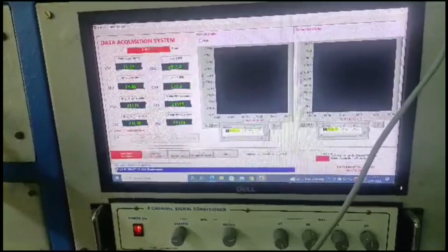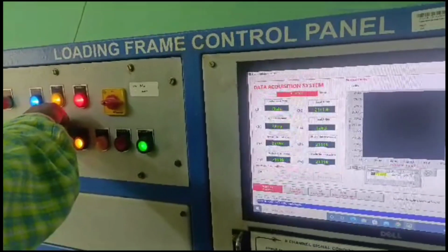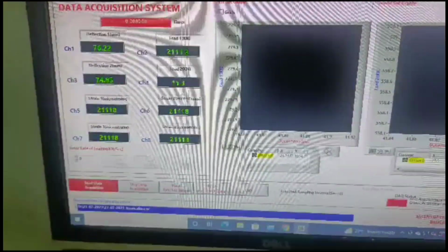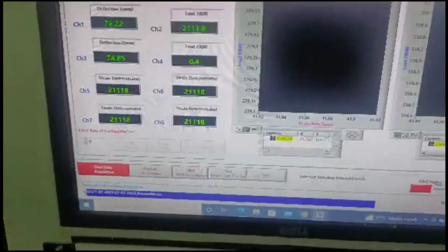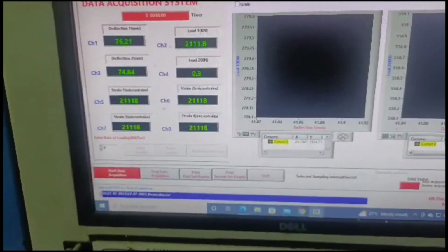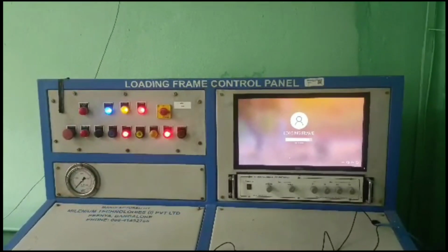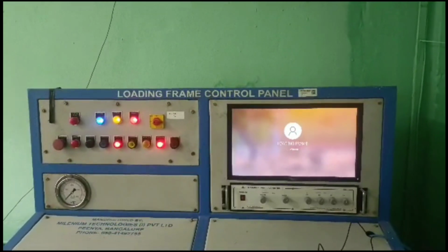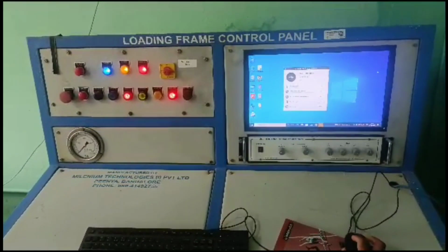The load shall be applied through two similar rollers mounted at the third points of the supporting span, spaced at 20 cm center to center. The load shall be divided equally between the two loading rollers, and all rollers shall be mounted in such a manner that the load is applied axially and without subjecting the specimen to any torsional stresses or restraints.